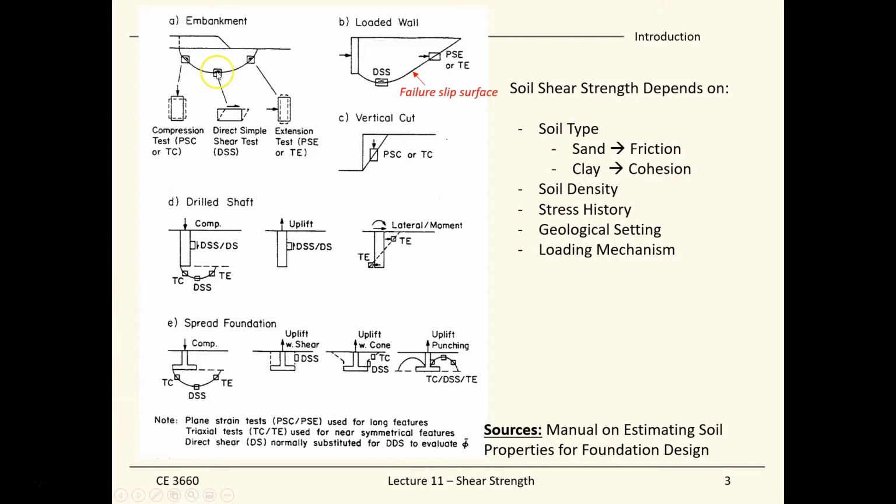At the bottom, it provides simple shear motion. You can imagine the soil elements that the slip surface cuts through. You have a top and bottom part, so it becomes a shear mechanism. The same applies to the wall and also the foundations: the bottom part of the slip surface is a shear loading mechanism.